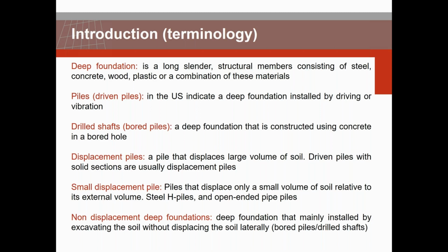Drilled shafts in the US are called bored piles in Europe and other countries. We also have displacement piles due to driving of the piles, small displacement piles that displace a small volume of soil relative to their external volume, and the non-displacement piles, mainly installed by excavating the soil.